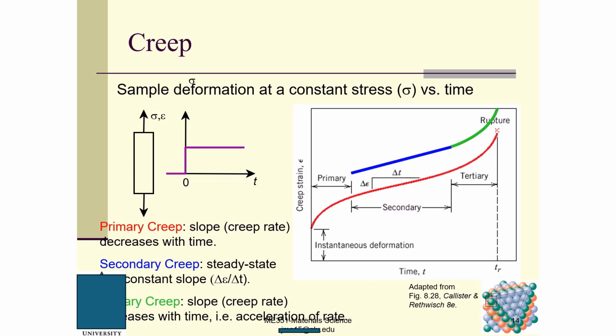And so here, primary creep. So here is the creep. Okay, so these are three stages: the primary creep, secondary creep, and tertiary creep. By the way, this figure is very, very similar to the figure for the fatigue life. We also have stage 1, stage 2, and stage 3. Stage 2 of fatigue life is called the Paris law. Paul Paris found this law, and it is called Paris law. You should know that this figure is very similar to the figure showing the fatigue life.